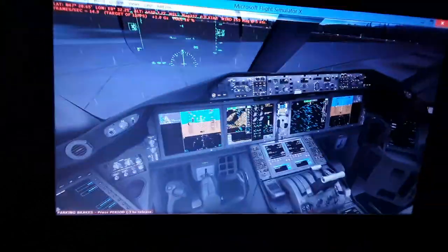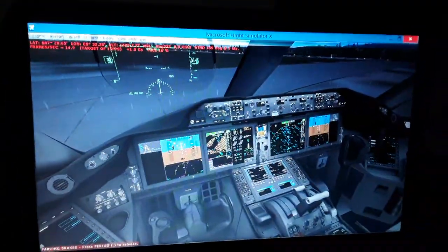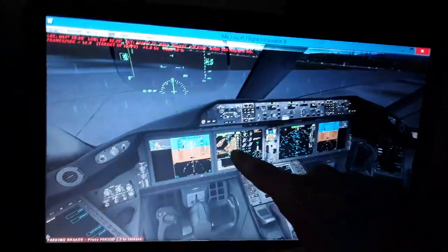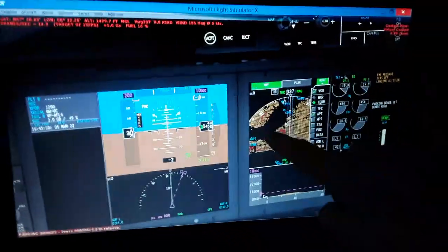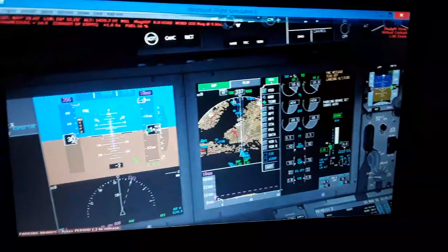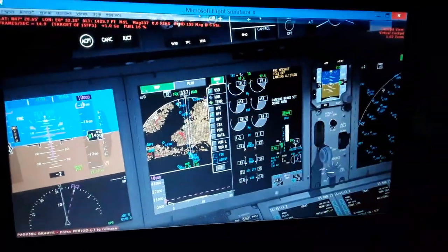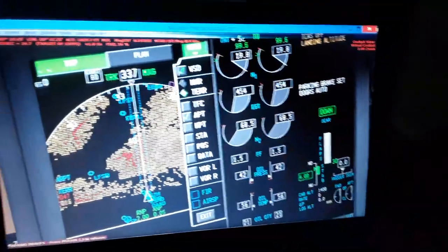And also this calculates the velocity closing in between our aircraft and the other aircraft, and gives us the TCAS system, the traffic collision advisory system, the warnings in the navigation display and in the primary flight display. So we have over here the navigation display. You can see it displays the terrain map, and we're going to see the flight plan later. We're going to see also the engine indications here. You can see the left and the right engine indications.